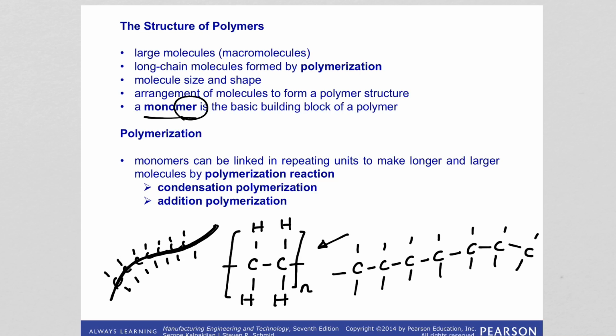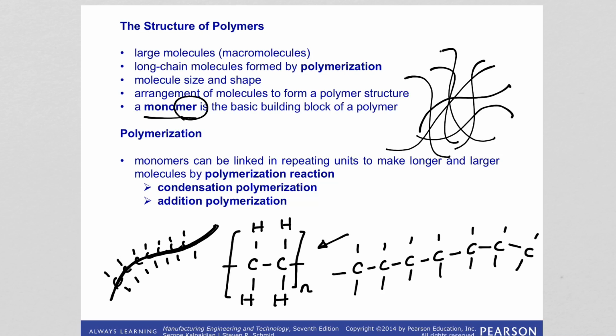This string will come together with many of these. So it's going to be like that. This is one, this is another, this is another. Think about spaghetti. So polymer structure is like that: a lot of carbon chains coming together, building the overall structure. Each of these chains has a carbon backbone, and there is a smallest repeating unit in all those chains that determines the main chemistry. These hydrogens can be replaced with chlorine, fluorine, or elements like silicon, and you can change the main chemistry.